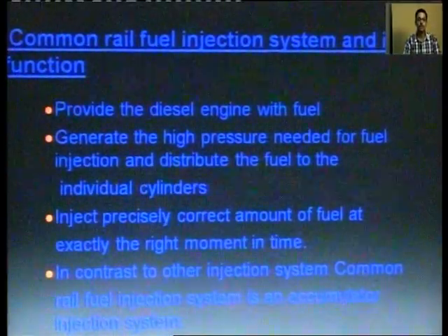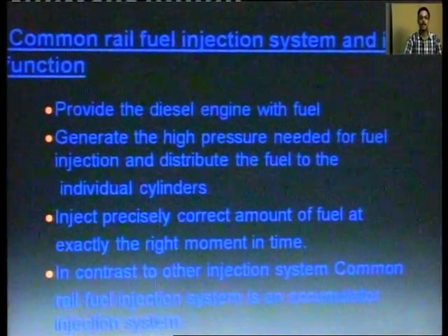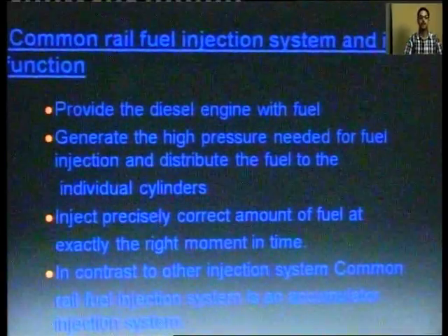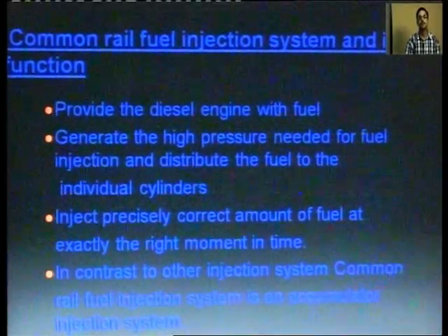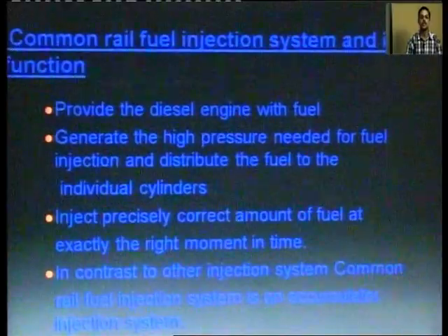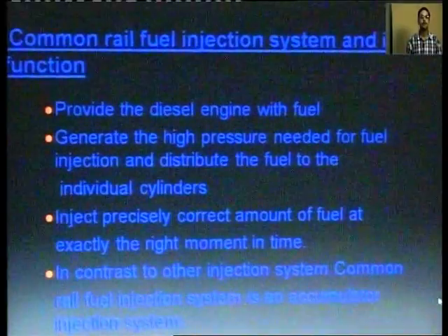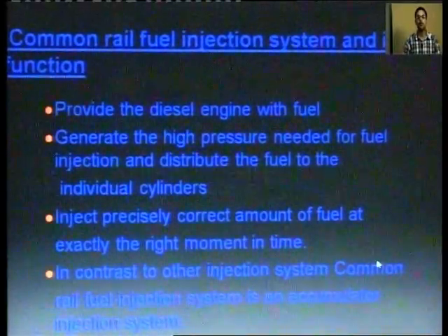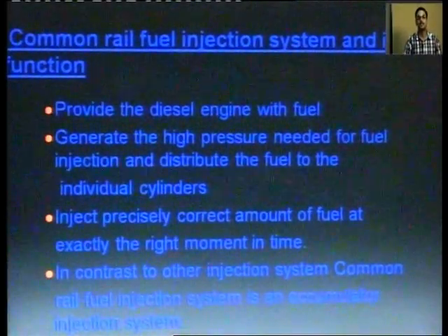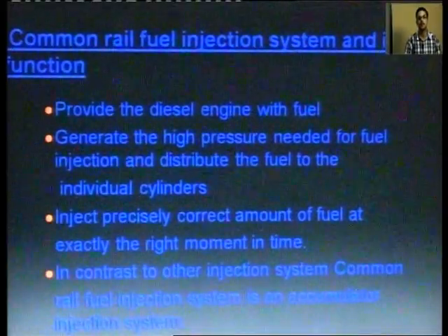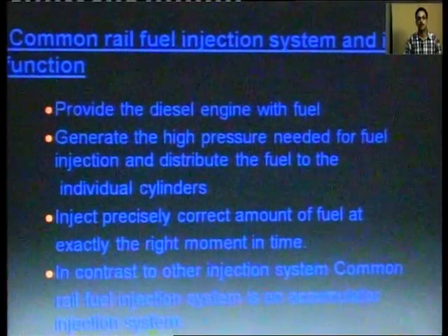The working of the engine is also based on this system, as the working medium, that is the CRDI system, will be the basic function of full engine working. This system also works as an accumulator in the case of injection. The fuel is firstly accumulated inside the common rail of the engine system, then it is further supplied to the individual injectors as per requirement.